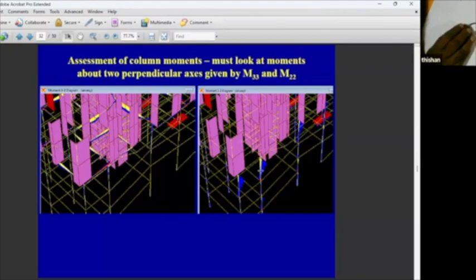So you can get a substantial moment in the column. The column moments at a lower level are much smaller than the column moment here. So there's a possibility for us to get a higher amount of reinforcement in the upper part of the column, just below the car park, than at the ground level. This is something that you might encounter in buildings with transfer floors.